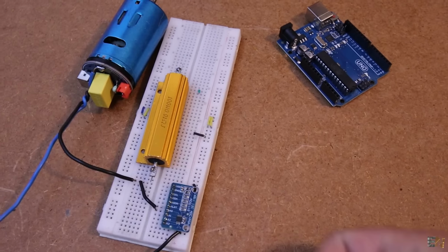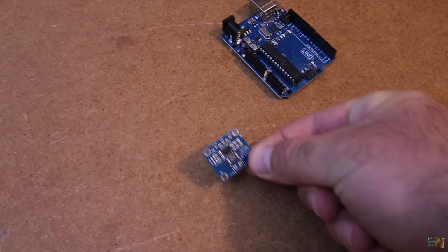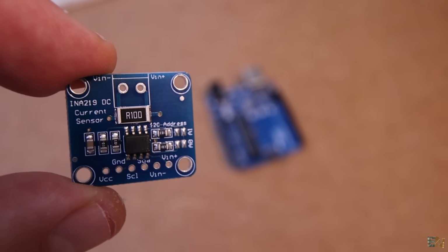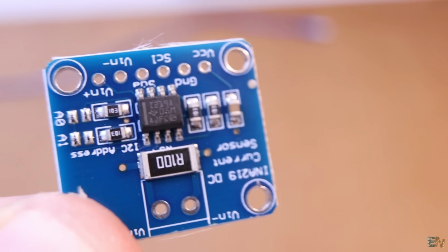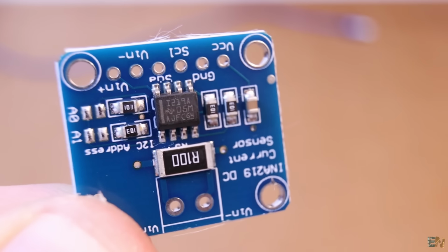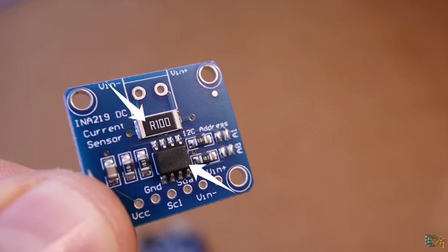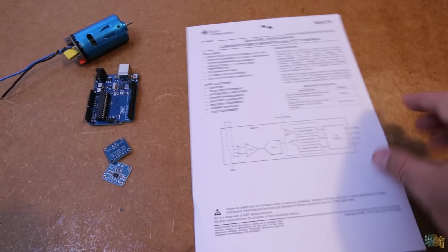So basically I want to change to another module, which is the INA 21 something. I'll place it here on the screen. This is based on a shunt resistor, which is a very small value of resistance, and with an operational amplifier you measure the voltage drop on that resistance. Since the current is voltage divided by the resistance and you know the resistance, by knowing the voltage you can get the current that is passing.